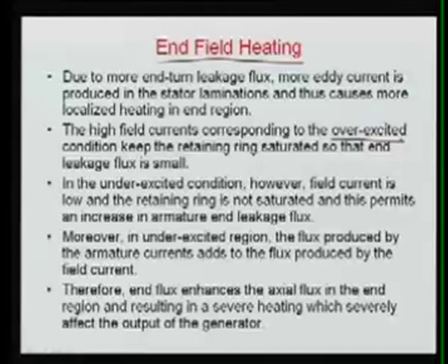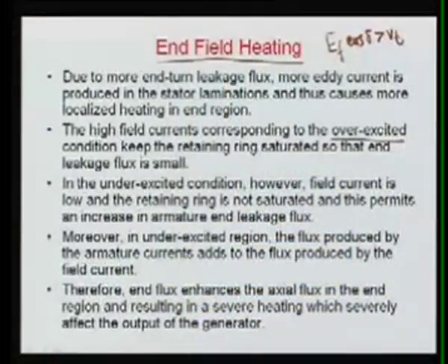Now, what is overexcited? In overexcited, if you remember, I said here Ef cos delta is greater than Vt. This is the case of a synchronous generator. However, in a motor it is the reverse, meaning Ef cos delta should be less than the terminal voltage, then it is called overexcited in the motor operation.